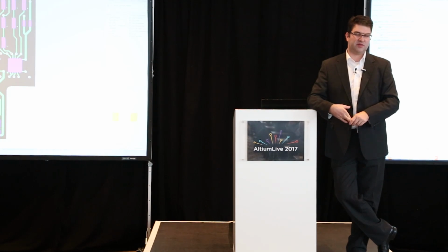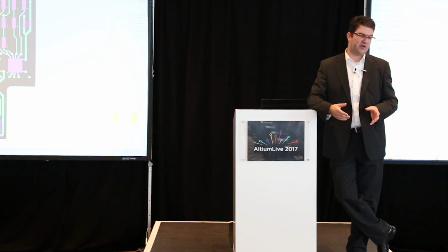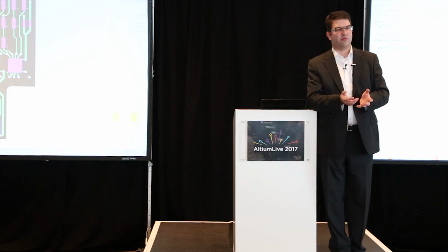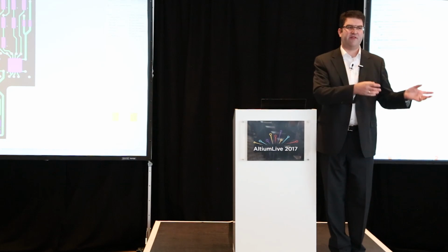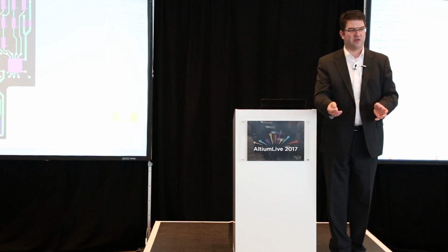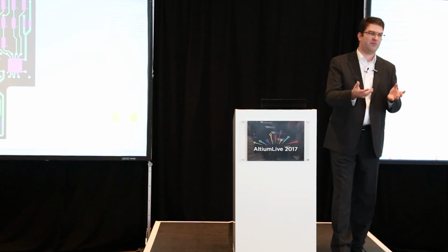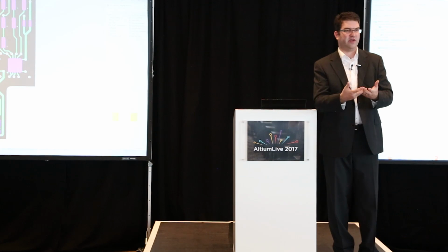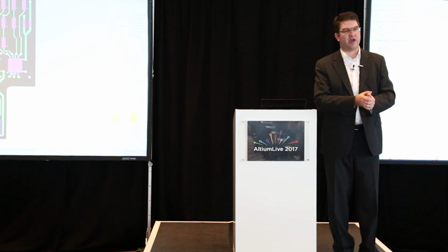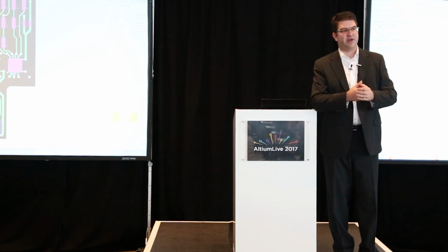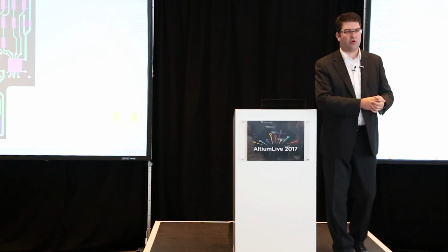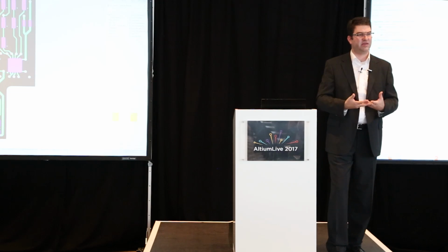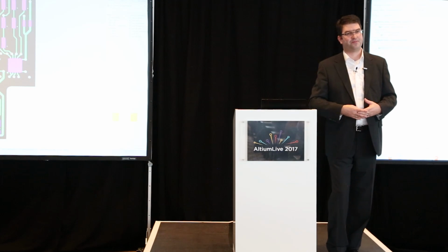Because what we do now, what you do not see as a board manufacturer, we have a script, for example, which is calculating the occupied volume from the components, and comparing this with the volume from the cutouts, and with the volume of free resin we could get from the prepregs to see if we can embed everything void-free, so that you do not get any air entrapments inside of the board. And yeah, 3D models, step files is normally a nominal point of view. So it's for viewing, it's okay, but for an actual check, it's not that easy to use, yes.